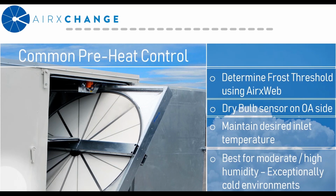As a rule of thumb, preheat frost control works best for applications that have a moderate to high indoor humidity or extremely low outdoor air temperatures. Some examples of these kinds of spaces would be buildings that have mechanical humidification, pools, spas, yoga studios, gymnasiums, athletic facilities, and so forth.